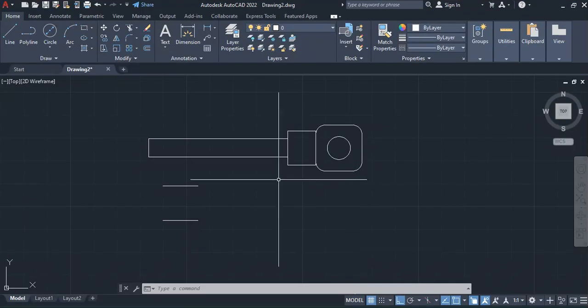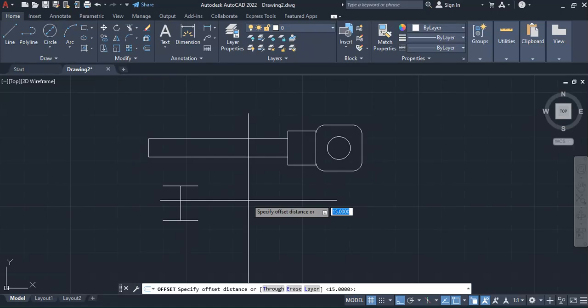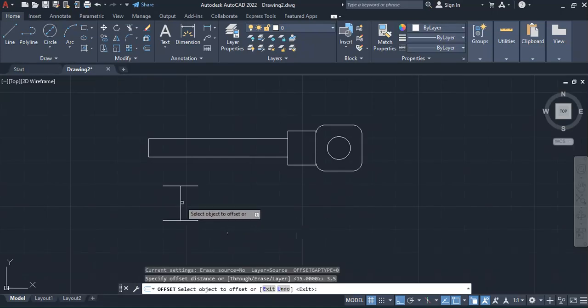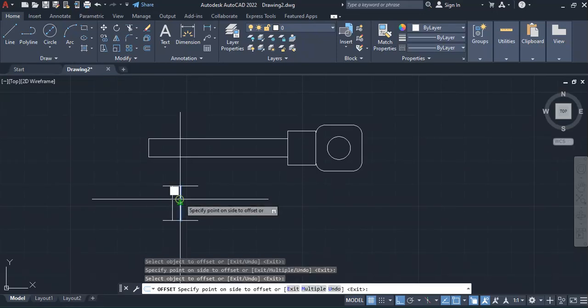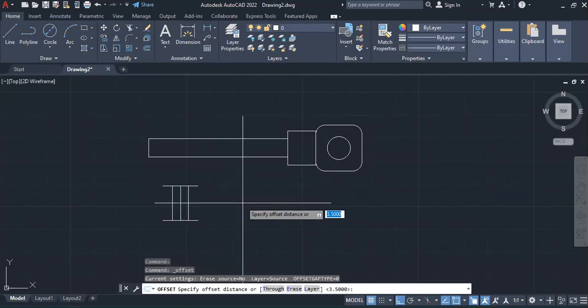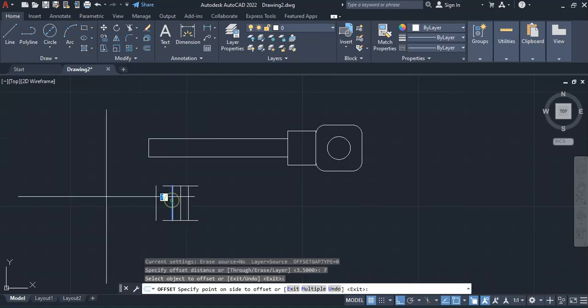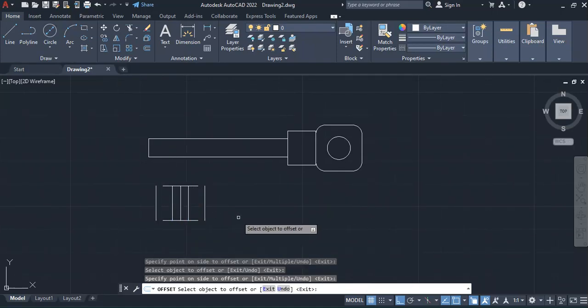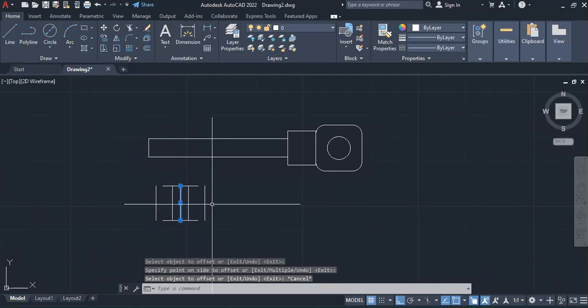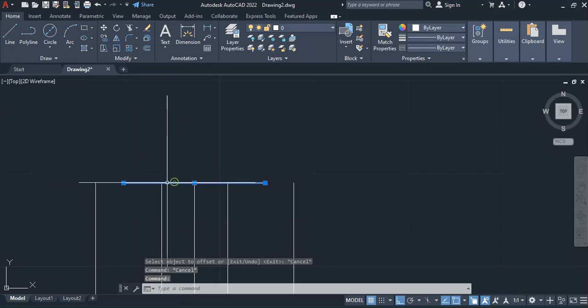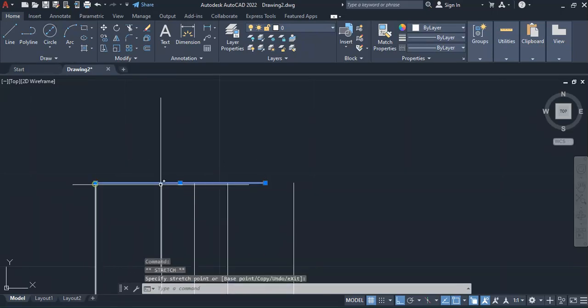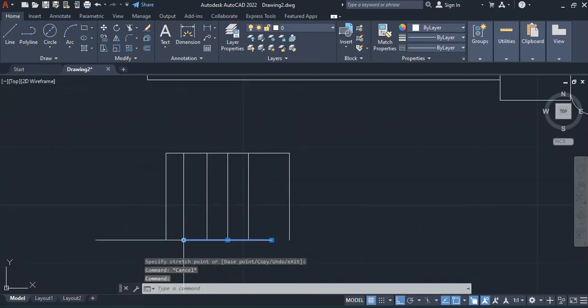So I come to the middle point, which is that one, then offset it a distance of 3.5 both sides. Then afterwards offset the end points a distance of 7 as such. Then I'll simply elongate these lines from that point. And the same to the bottom points.